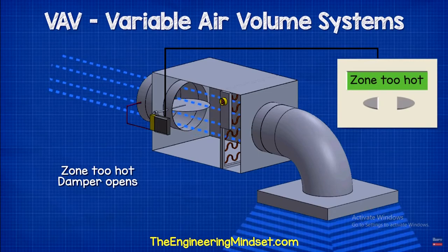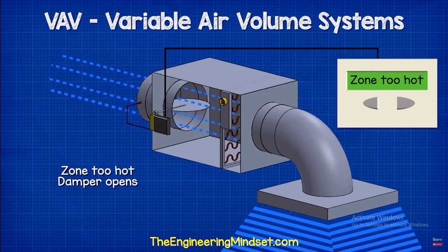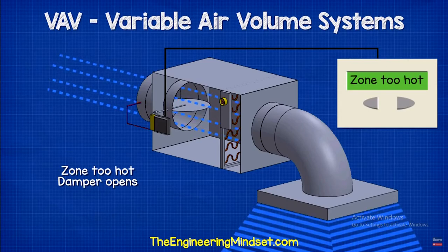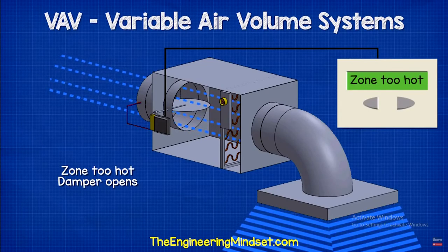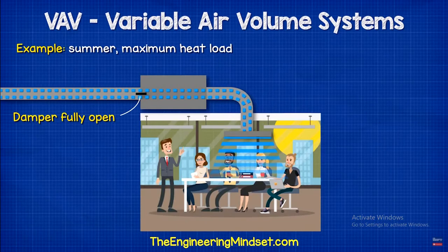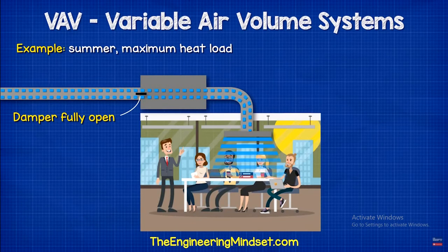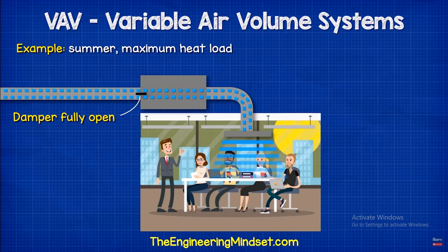You can get fan-assisted VAV boxes. There are many variations, but this is a simple example. It's essentially the same as a regular VAV terminal, except we have this extra section which usually contains a small filter and a fan. The fan allows air to be pulled in from the room. This air is dirty, so we pass it through the filter to stop the dust from collecting inside the fan, the ductwork, or even the heating element.